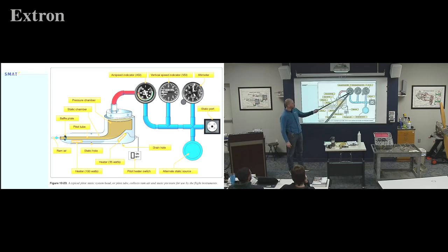And then our airspeed indicator, well, that's a pressure sensing device in that it's going to compare ram air pressure into my pitot tube with the static pressure. So if you are not flying through the air forward, it's going to say, well, the pressure of my ram air is the exact same pressure as what's alongside my aircraft, right?